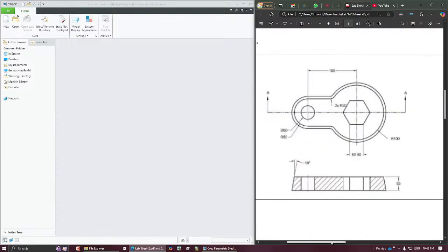And you can see here that the dimensions are defined for the smaller, inside boundary. So whatever 100 radius has been given, it is given for the smaller circle here, and the radius 50 is also given for the inside circle. So we'll have to define the top boundary first, and then extrude it by a distance of 50, and after that subtract these two entities.